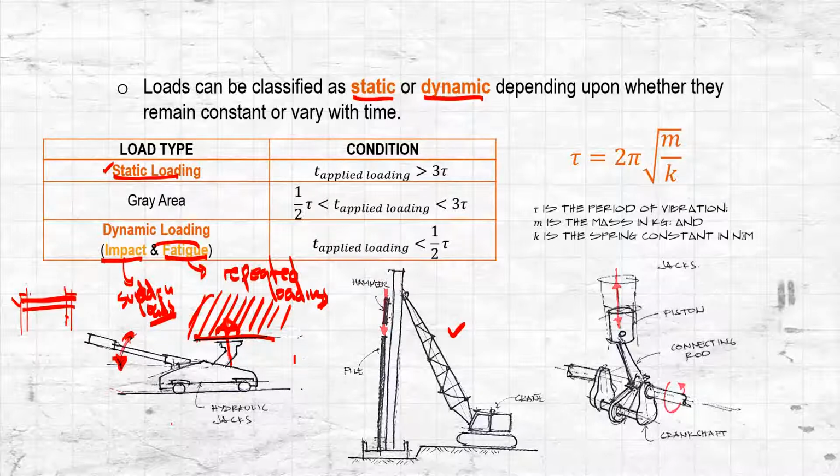If there are foreign materials or hard foreign materials, like for example stones, then it can cause impact on the peg tooth of the threshing cylinder. Okay, so that impact load is actually much larger than the static loadings. If the part is designed only for static loadings, then that's going to be a problem if we don't consider the impact loadings.